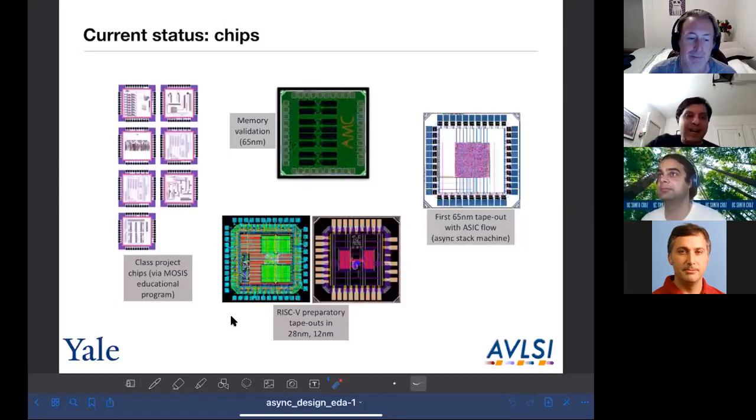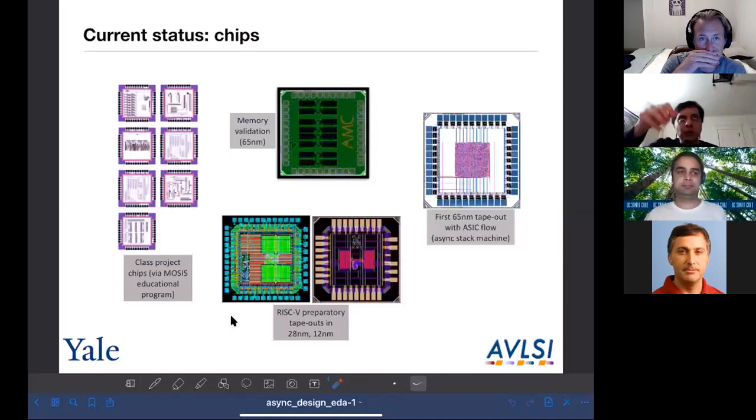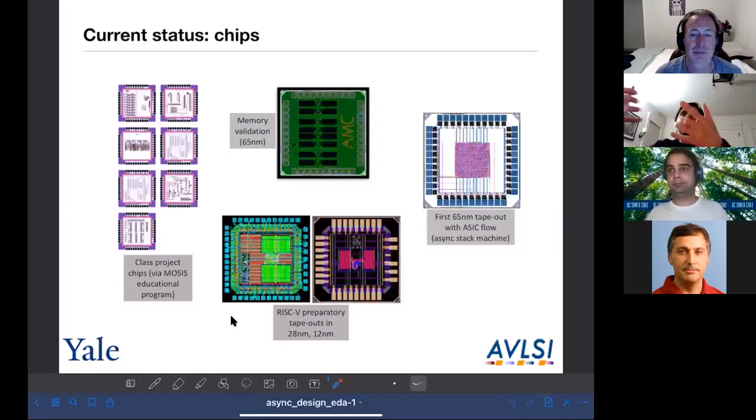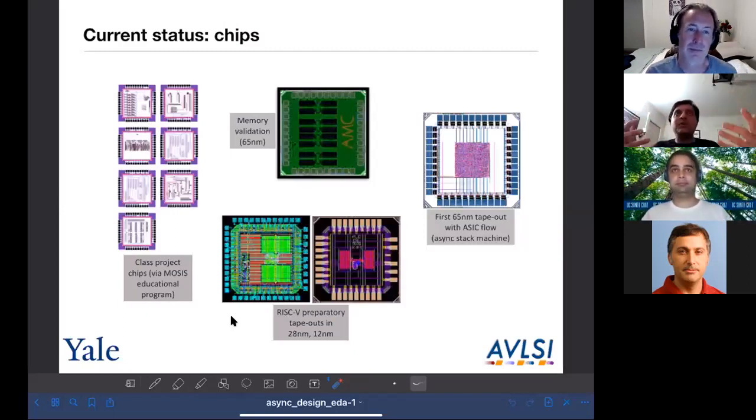Yes. So one of the things that our flow does is you can decide whatever you want. You can decide what your gates are. It's up to you. So it's very, very customizable. You can build your logic synthesis engine, target your favorite circuit family. And when you run through our flow, it'll say, okay, I'll read in the standard cell description that I have, and it'll try to match the gates that you have against what's in the standard cell library. And then it will tell you, I'm sorry, you have the following list of missing cells.